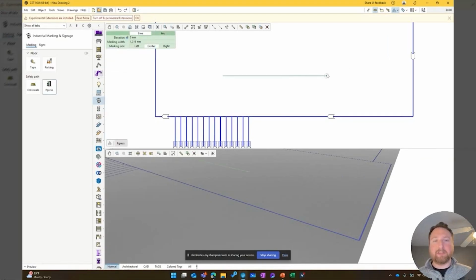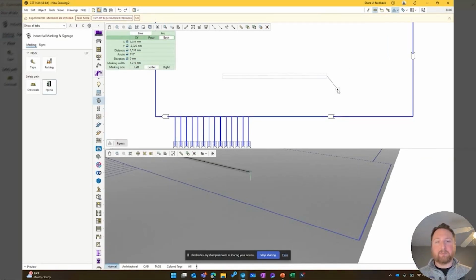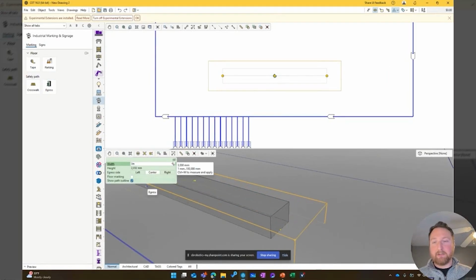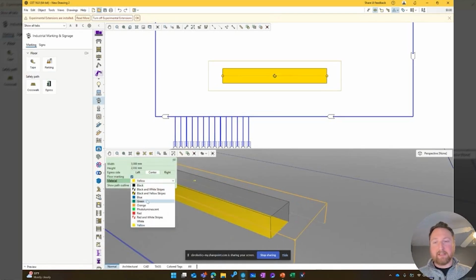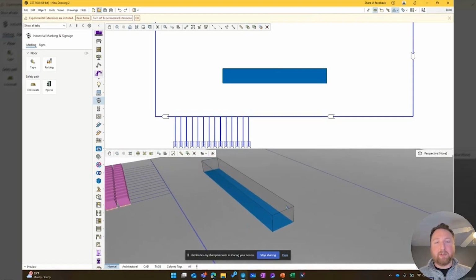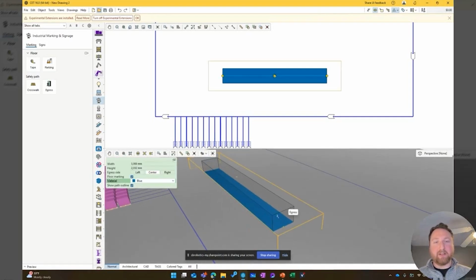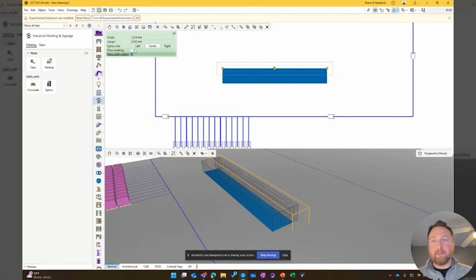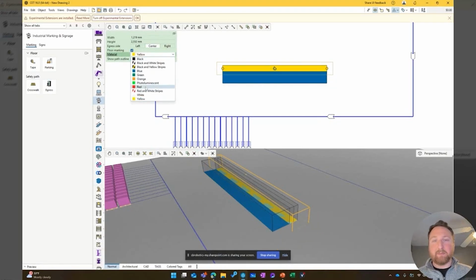So we talked about using these egress paths just as exactly that, as egress. If you know you need a 3-meter aisle, you can easily do that. Say I want all my automatic forklift paths to be blue, color it there and plan around that. Something else I'll use a lot with this is, instead of just drawing the path, actually using this to draw the safety barriers.